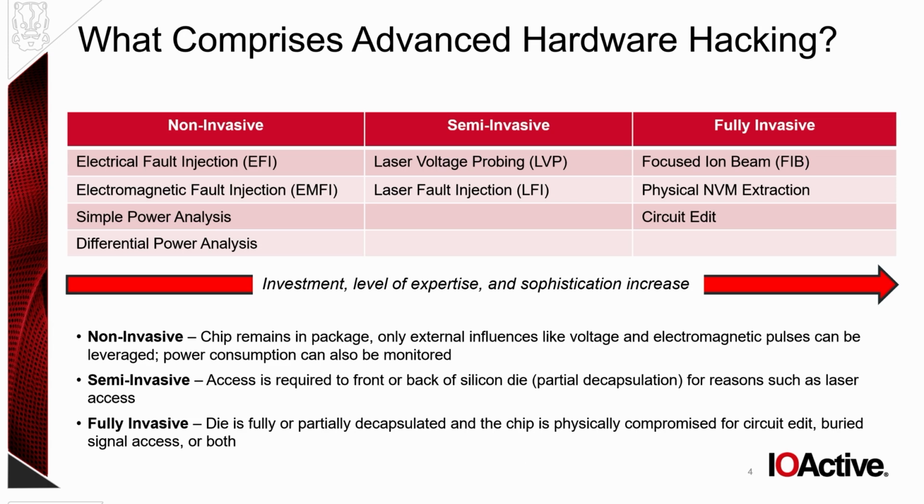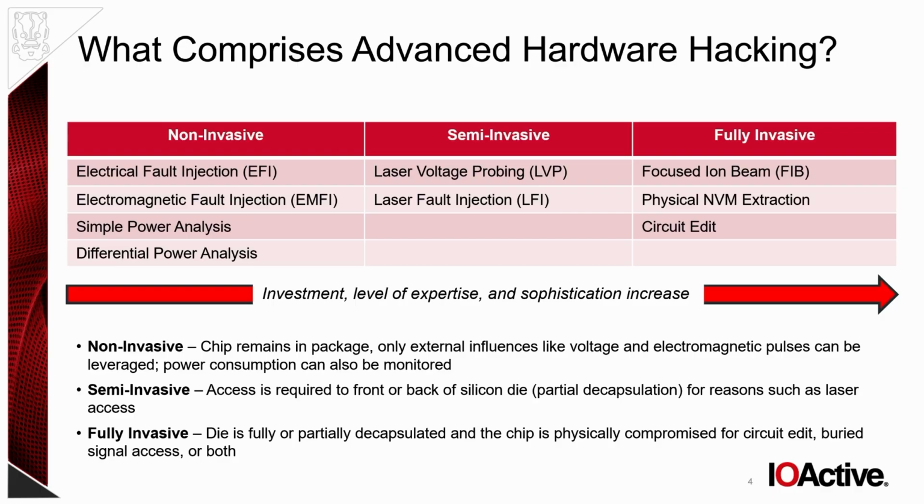On the left-hand side, we have non-invasive techniques such as glitching, electromagnetic fault injection, electrical fault injection, all kinds of side channel attacks. So we do this in Madrid. We have a lab there, and we have a bunch of experts who are all over this. Then in between, there's a semi-invasive selection of attacks that we try and emulate to inform people that are making chips.